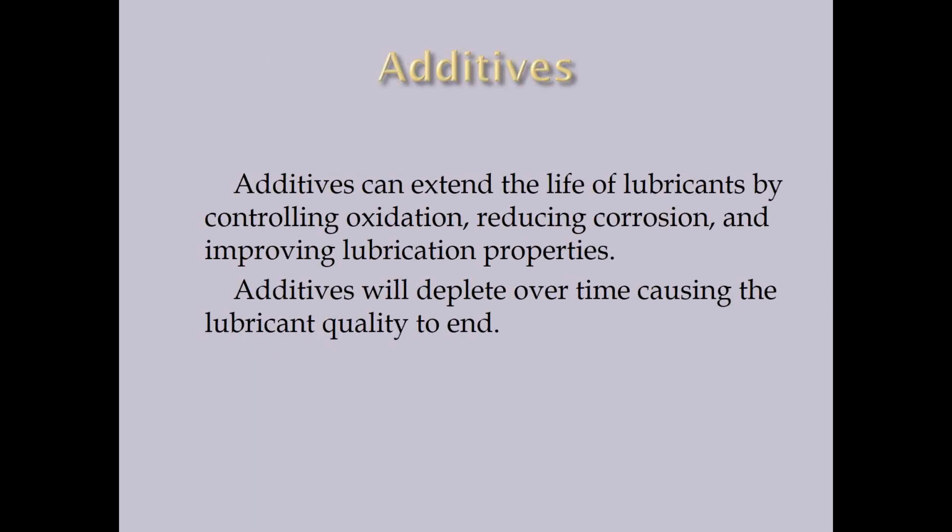I want to touch on additives. In all the lubricants you buy, there's additive packages in there. And these additives are in there to keep the petroleum oils from oxidizing as fast. There's additives in there to reduce corrosion and rust. But these additives are in there to improve its lubrication properties. But again, these additives deplete over time.